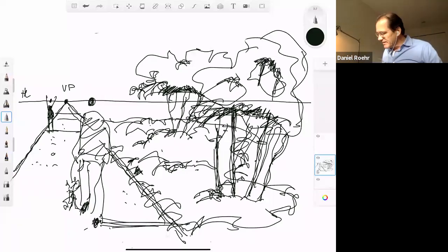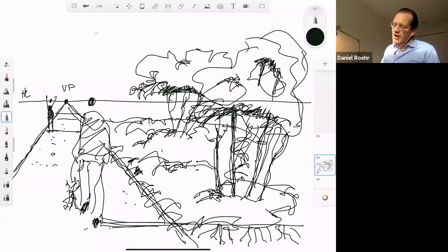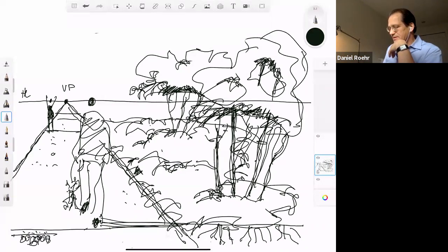The other thing is what I think is really important. You can also put underneath the root growth and indicate, you know, if this is, let's say, on a green roof, you can also think about how much space is needed for the roots. So it makes you think again, X-ray, the perspective, you can kind of make it in a section, and you can continue that here and could say what kind of layer of gravel, what underlying hardcore is underneath to keep the gravel, what kind of surface it is. So you can communicate all those things in that drawing as well. So I think that's really important.